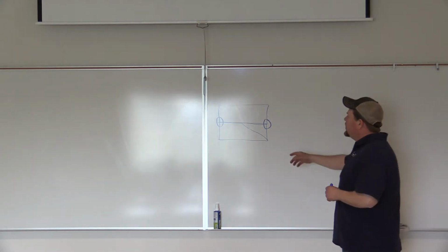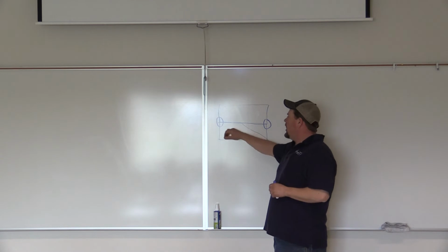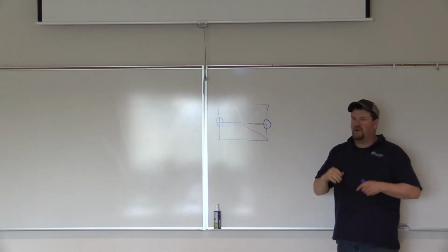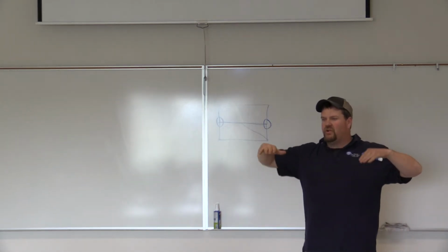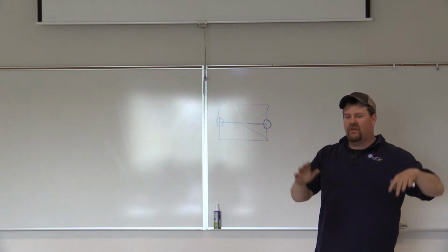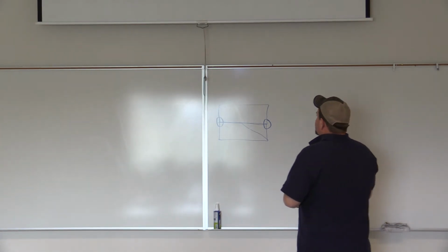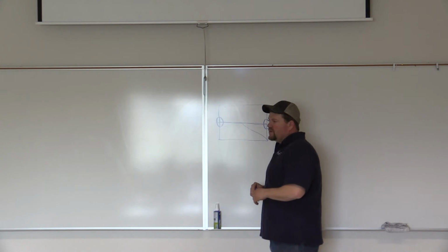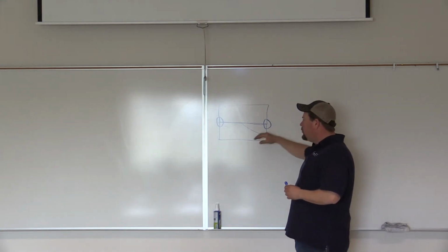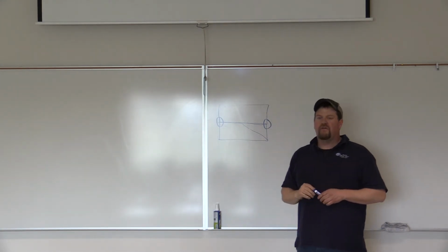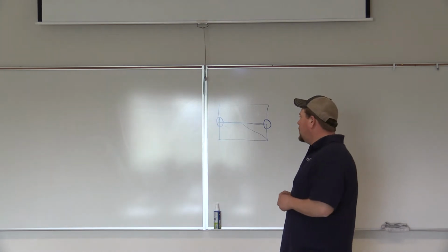And if you start to see that it's missing, it got a broken or a crack, then you know this piece is getting thinner, and you're putting a lot more pressure on the blade, and you're going to start tearing up the asphalt as well. So that's when you come back in, you might be able to weld this back on. You don't want a deep weld because you want it to be able to shear it off if it gets in a bad jam, all right?